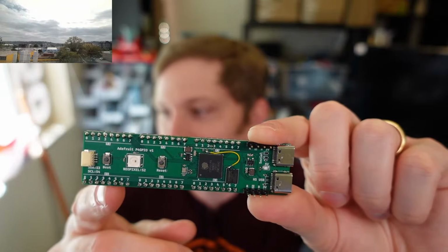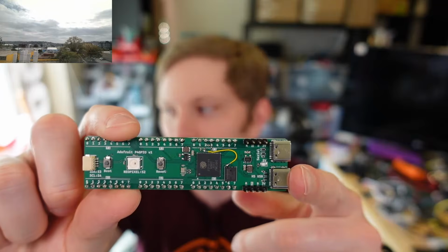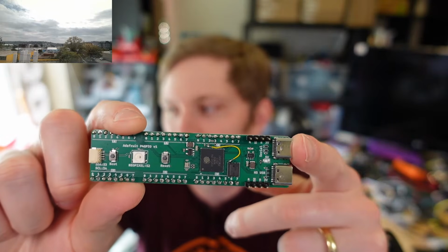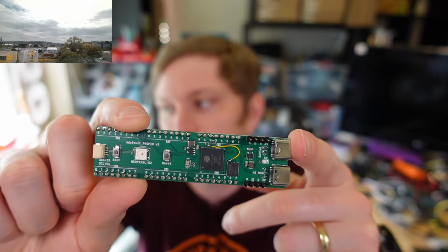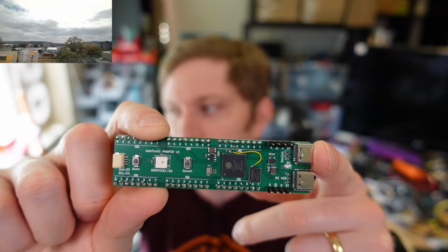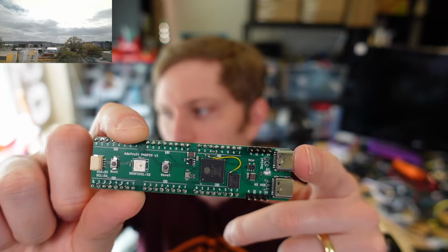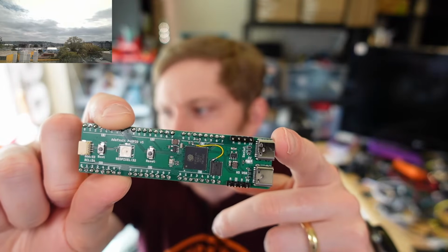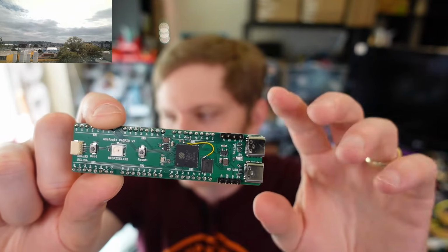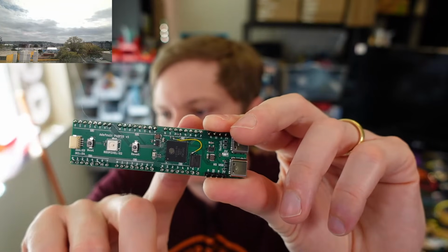So what does this board have? I'm backwards, so this board has two USBs. One is the high-speed USB, and one is the USB to serial JTAG. The serial JTAG USB takes two of those 55 GPIO. The high-speed USB pins are on dedicated pins, so you lose two there. And then there are two bootstrapping ones, and then a NeoPixel one. So I got 48 I/O out, so I have 6 headers of 8 pins.